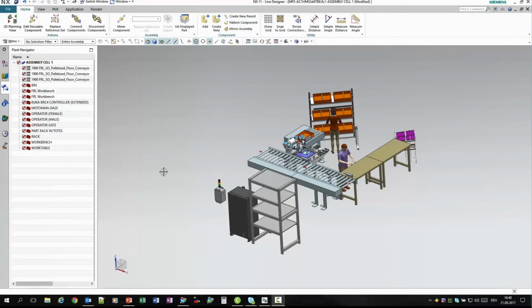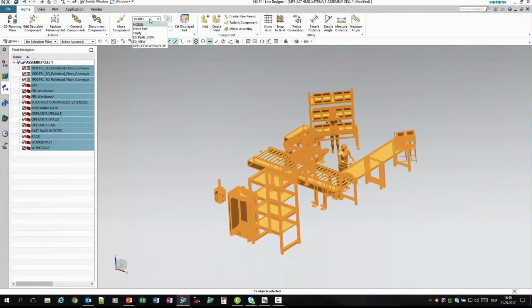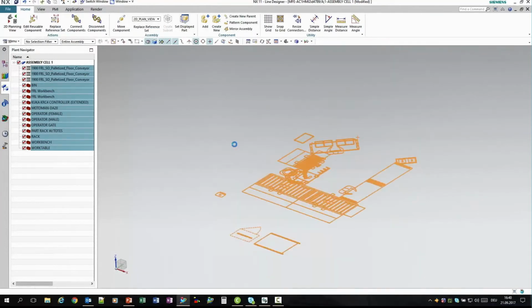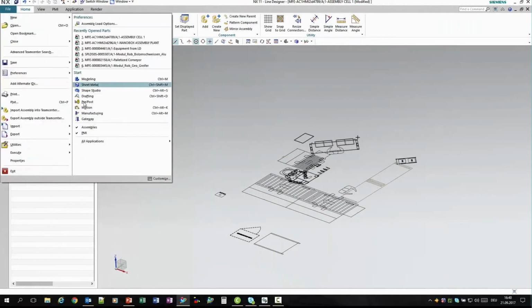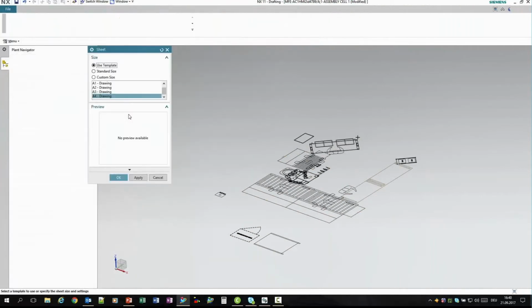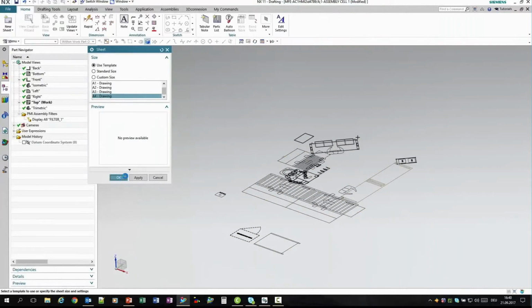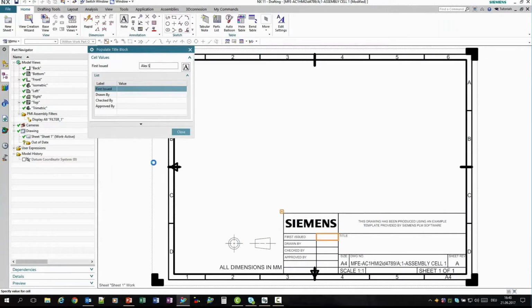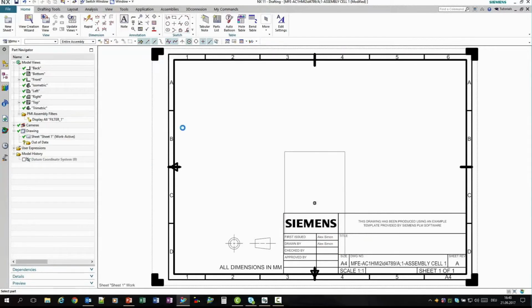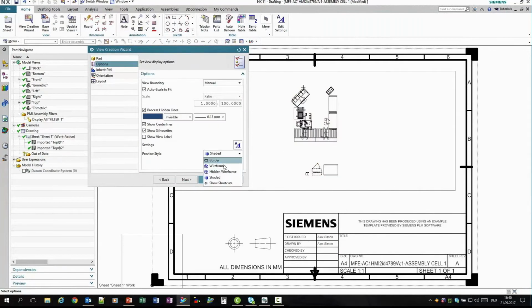So, going to drawings, right? Here I have this 3D file, but a lot of companies like flat 2D drawings. There's a button here, I can hit flatten and it creates a nice flat drawing for me, right? So I now can show that drawing and I'm just going to real quickly put some title block information in here and create a drawing for this. And there's my drawing, right? So it shows all the pieces that I have in there.